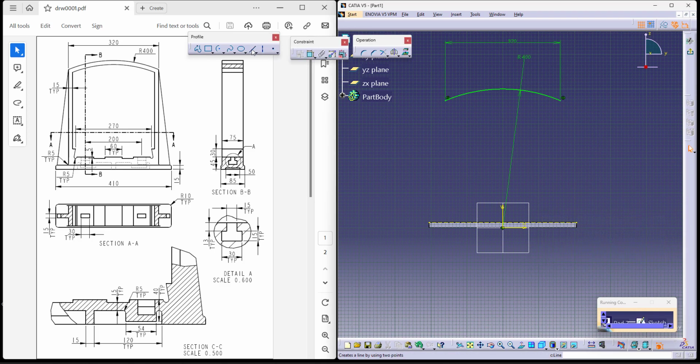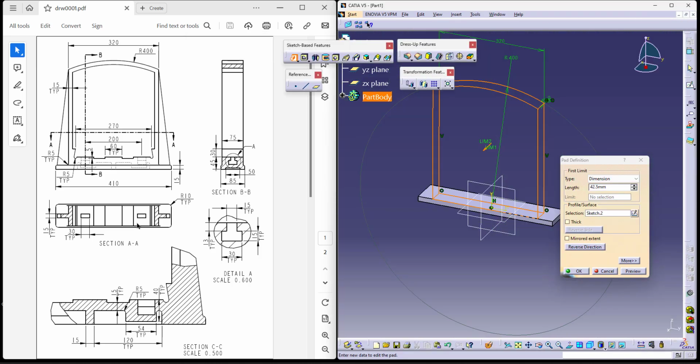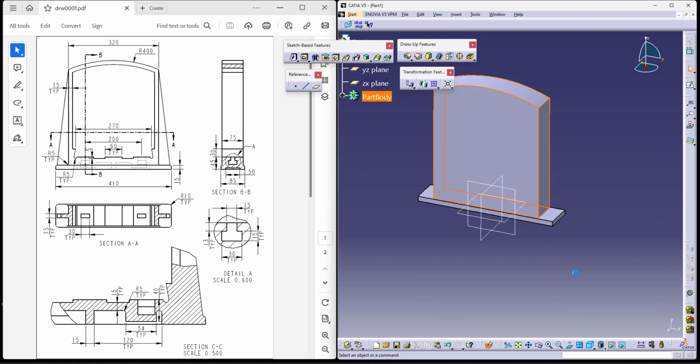So let's try to take those lines at the moment and try to join them with the base. Similarly, I need another line over here so I can join them with the base. Now I can join this as well. Now the sketch is actually supposed to be completely constrained, so let's try to see what's wrong. Okay, it's not coincident on the exact point, so let me try to use a coincident constraint. Now try to close the base. Now this particular profile is added equally on both the sides to 75. So I can just add them using mirrored extent to 75, which adds the material.